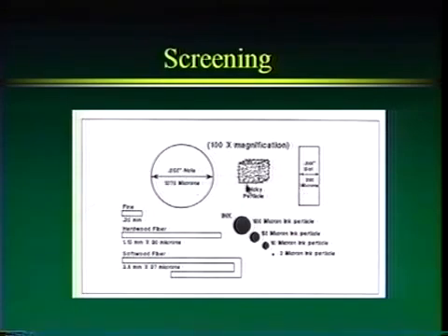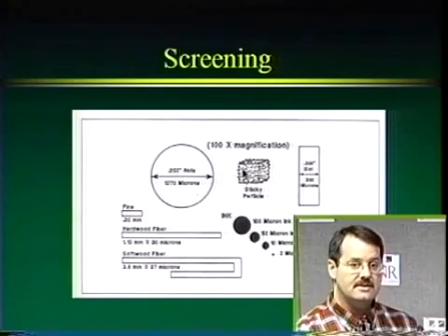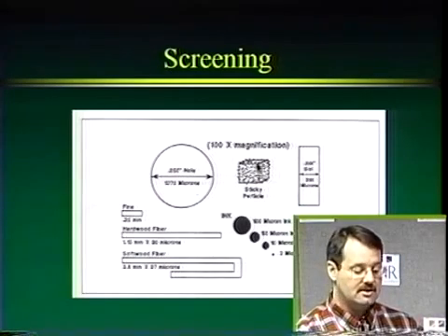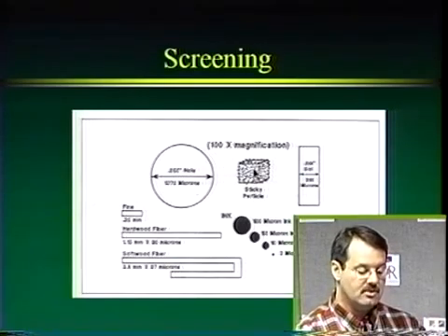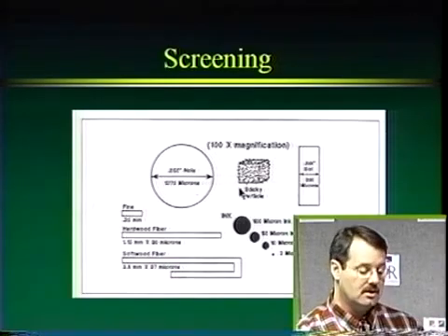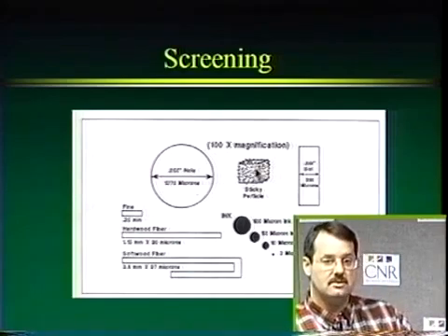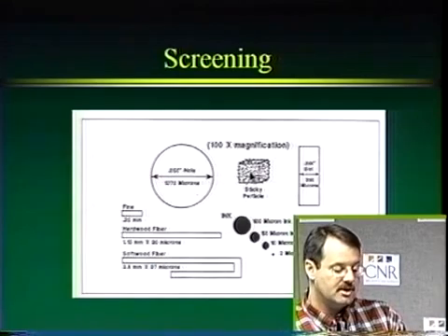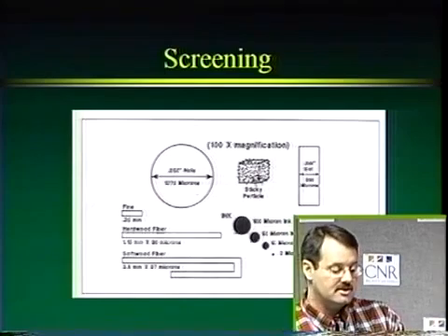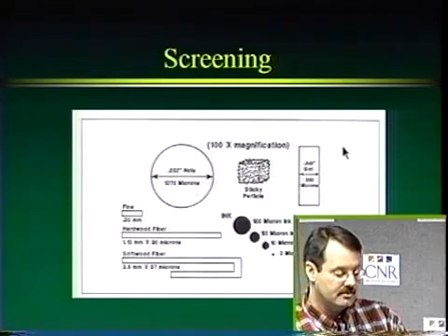A sticky particle is shown right here, and sticky particles are often really soft and deformable. And their size varies from very small to very large. Here's a medium-sized sticky particle. It looks like it's going to be about 200 microns wide, and this would probably pass through the slot and the hole. And even sticky particles that are larger than these openings might pass through, because the forces in the screen may extrude that sticky particle, because it's soft and deformable, through these openings.